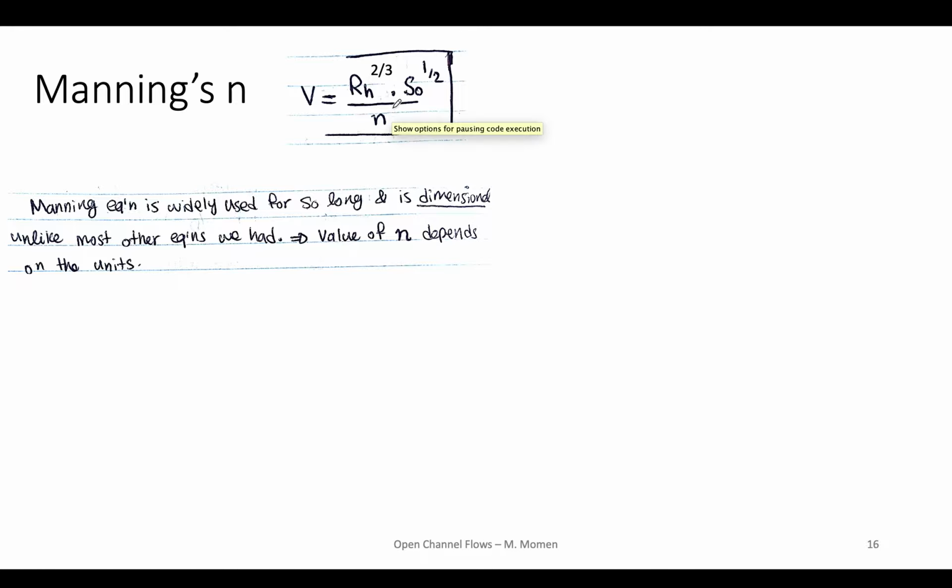We came up with that using some momentum equation, and also assuming a very large Reynolds number, where the n or the k in those equations is independent of viscosity, and is only a function of roughness of the channel and the dynamic pressure. So using all of those assumptions, as well as the assumption that the flow is uniform, we got to this equation, which is known as the Manning's equation.